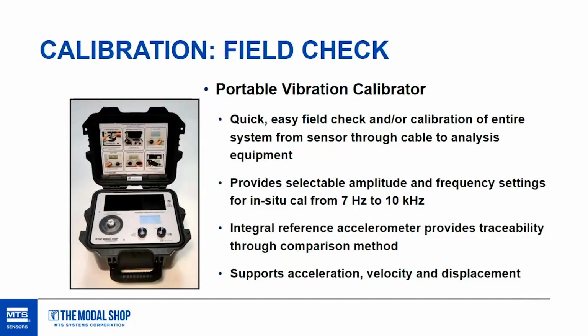And you can radio into a different operator to confirm that at the time that you're setting these settings out in the plant floor, they're actually seeing what they expect back on that system. So it's an upgraded version of that, and more often these days, portable calibrators like this include more of an analysis of uncertainty. There's versions of these that can take that output signal from the test transducer and actually, instead of running it all the way back to a station, just run it right back into the portable calibrator, and you effectively have just a shaker with two inputs. So you can measure those two V's, the two voltages, the one from the reference internally and the voltage from the test sensor, and get out a calibration value at different frequencies for a unit like this. So there's more options for this type of calibrator.